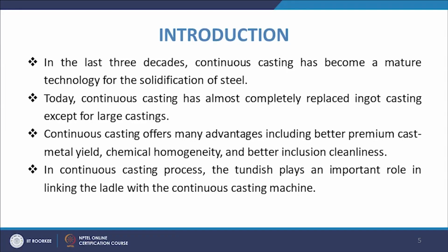Now, what has been happening ever since the continuous casting process came into the picture? In the last 3 to 4 decades, continuous casting has become a mature technology for the solidification of steel, and today it has almost completely replaced ingot casting, except for very very large castings. There we still go for ingots, but otherwise we have completely replaced that process with continuous casting.